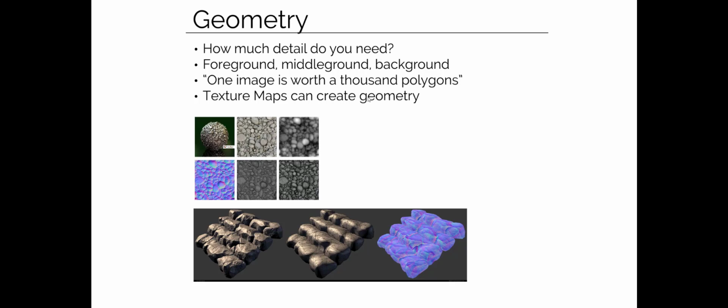And so if you have to do that within the geometry, there's a plugin in SketchUp called Round Corner. You can do that, but it's an enormous amount of work. Well, now in Lumion, you just pick a material and say round the corners and adjust how much you want. It automatically does that for you. So it saves a lot of time, keeps the model simple, and does all the work in rendering.